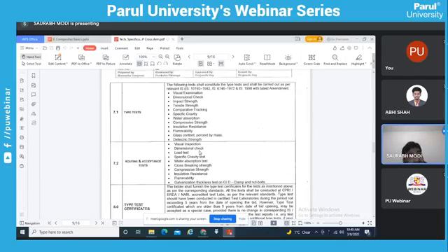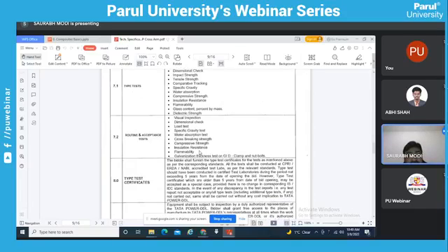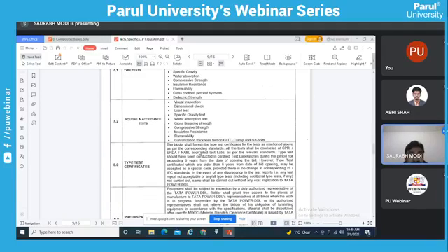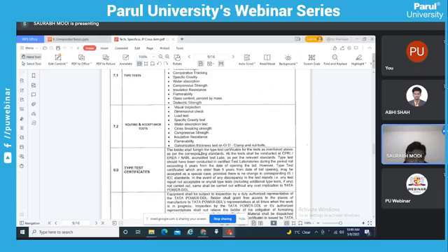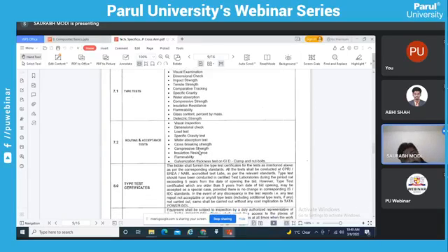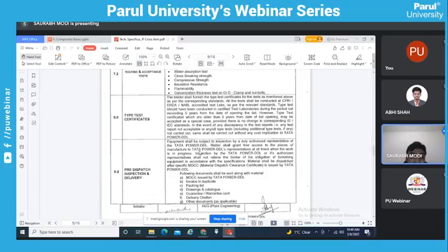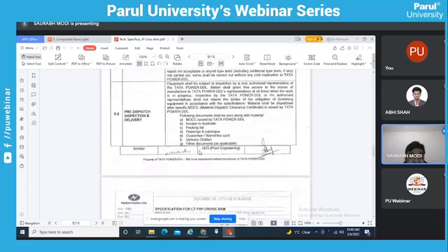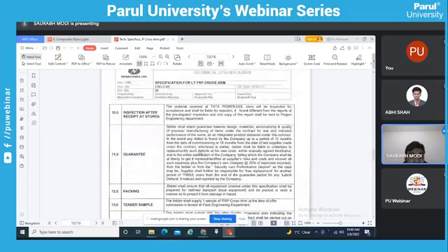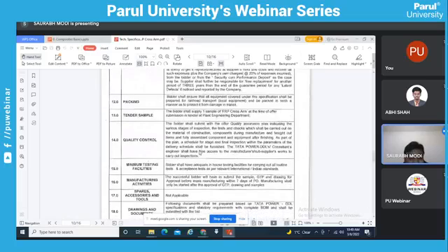There is a difference between type test and acceptance test. Once type test is done for the prototype, then for each and every lot that we produce, we will do routine and acceptance tests, but routine and acceptance tests are done in our in-house lab. We also have a lab. So that you can do in your in-house lab, but for the sake of trust, the initial prototype test to prove your capability to manufacture, you need to do as a type test in any NABL approved lab.